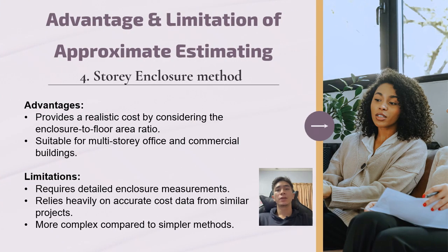Lastly, the storey enclosure method provides a more realistic cost because it considers the ratio of the floor area to the total building enclosure, including walls, floors, and roof. The advantages are it is best suited for multi-storey office or commercial buildings where enclosure affects cost significantly.